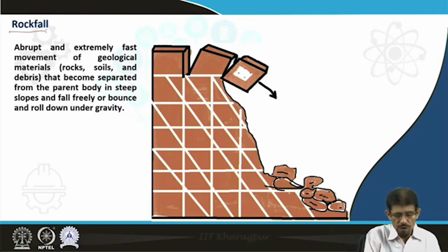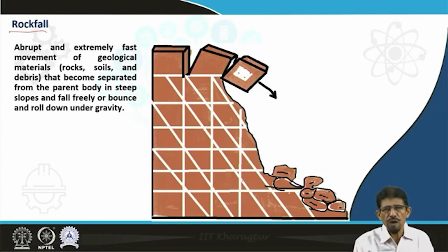First we are going to discuss the rock fall. You can see the rock fall is a form where the ground or strata is traversed by a number of joints, here J1, J2, J3 or more, which can divide the whole rock strata into different blocks. When water enters inside, it pushes these blocks, and due to gravitational pull the blocks are ready to move downward.